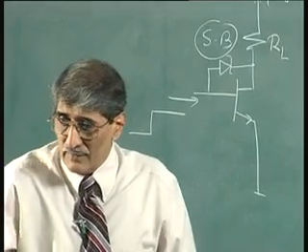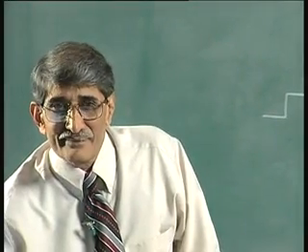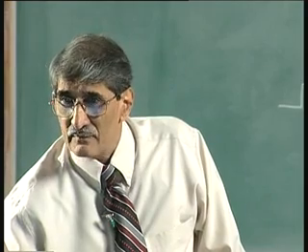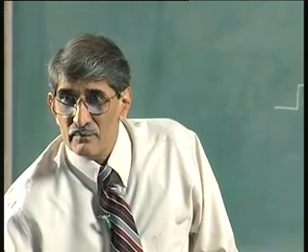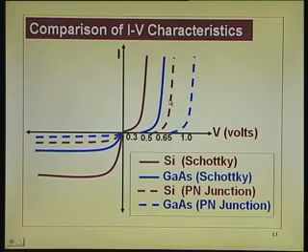So, now you can see this diagram. Instead of 0.6 volts here, the PN junction across when it goes into saturation, you have put a Schottky here, this dotted one, the first one. The voltage drop across that is 0.3 volts. So, the voltage drop across the collector base junction, which is forward biased, is now 0.3 volts. So, it has not gone so much into deep saturation.